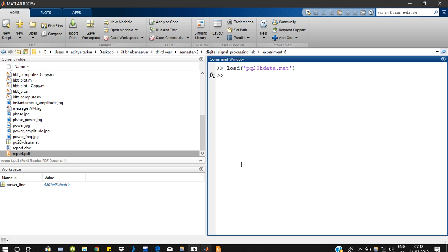One, a simple convolution that I just explained, or you can perform a Fourier transform and change properties there. In my case, I have an amplitude modulated signal, a frequency modulated signal, a power line signal, and an exponentially decaying signal. Let us see if we can see the instantaneous amplitude in an AM modulated signal and whether we get a message out of it or not.